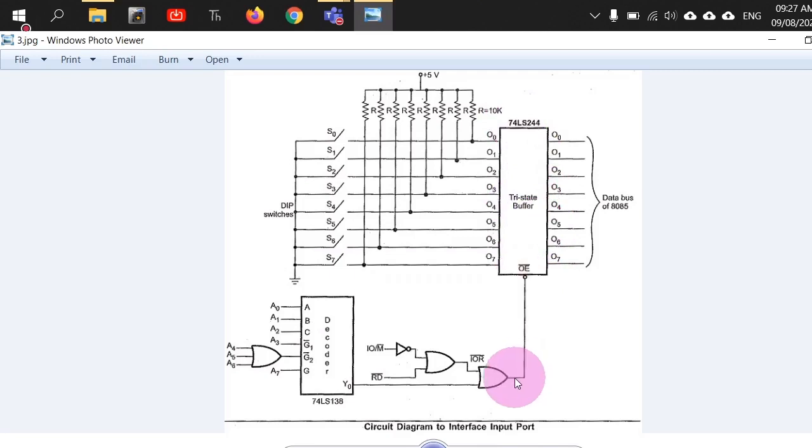So when do I want this chip to be activated? It will be decided by the microprocessor. Suppose an in or out command is there in the program. So what my microprocessor will do is it will have some address, and that address should be used to enable this particular chip. So that is what is there.